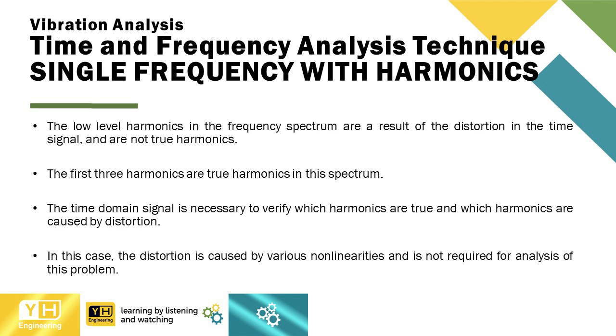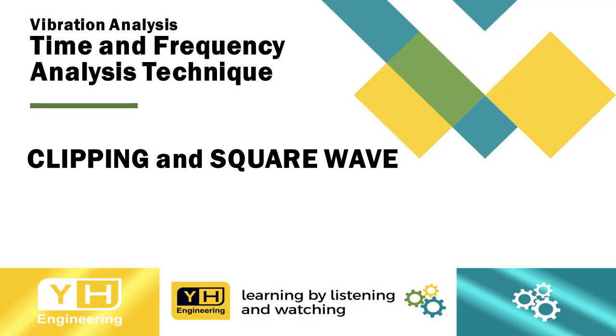The time domain signal is necessary to verify which harmonics are true and which harmonics are caused by distortion. In this case, the distortion is caused by various non-linearities and is not required for analysis of this problem. Vibration analysis: time and frequency analysis technique.